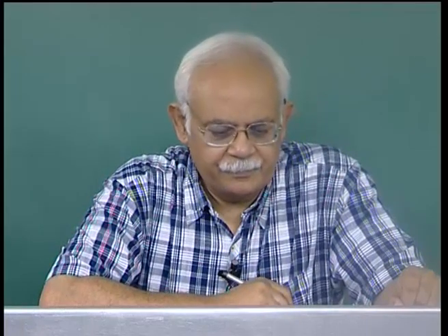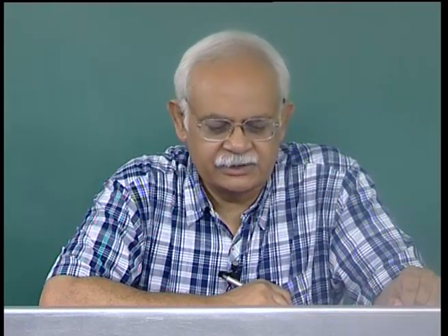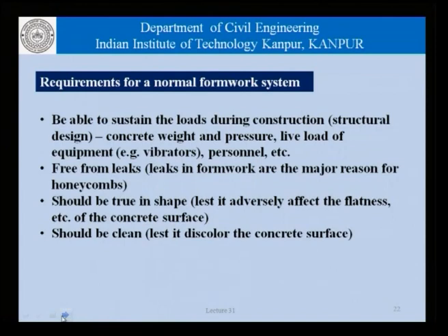Now, reiterating these requirements, it should be able to sustain the loads during construction, and that is more or less similar to that of structural design. The kind of loads that could be are concrete weight and pressure, the live load of equipment, that is vibrators and so on, personnel, that is people who will be moving around on the formwork or on the concrete during construction. You can think in terms of a slab while it is being cast.